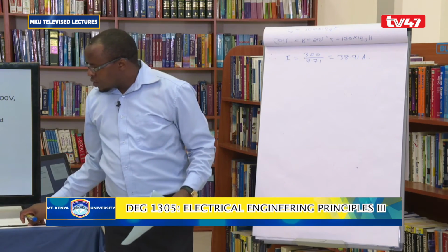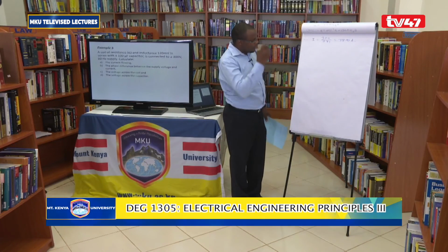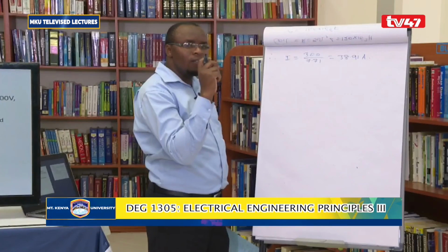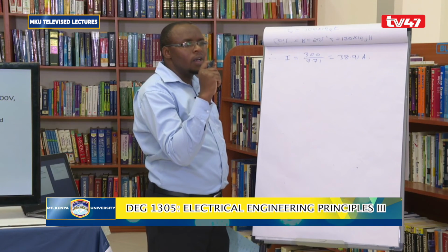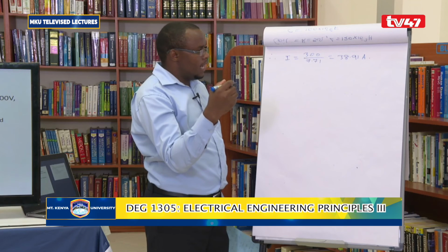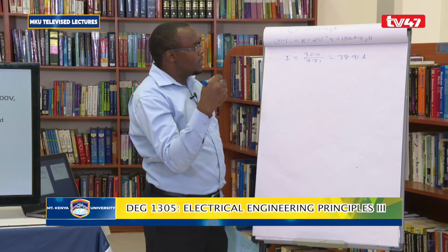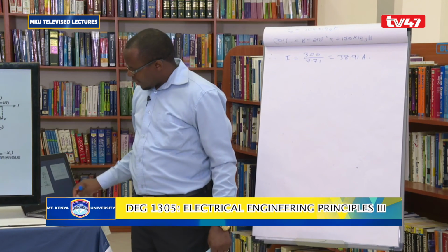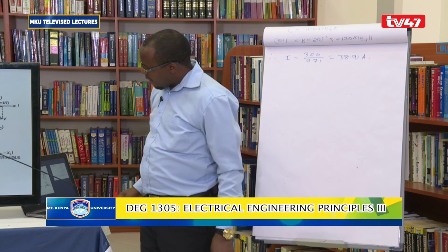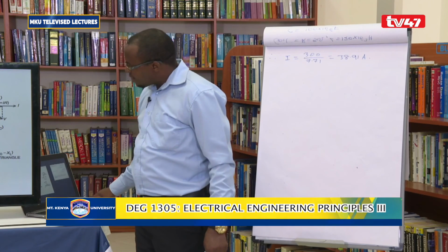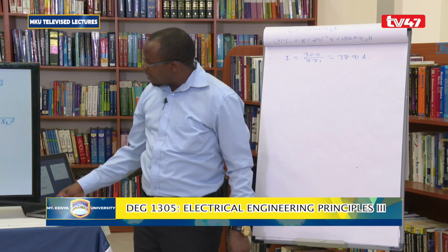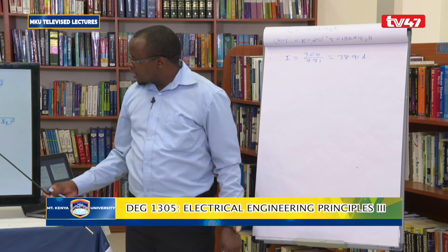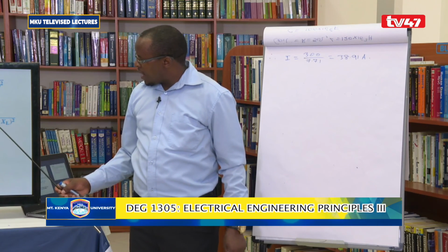So here, to get the phase difference, we have seen that in the coil we have the resistance and the inductance, and from the phasor diagram which we had here, to get this angle, we have seen that when XL is greater than XC, the formula that you are going to use is this. You get the tan inverse of this one over this.